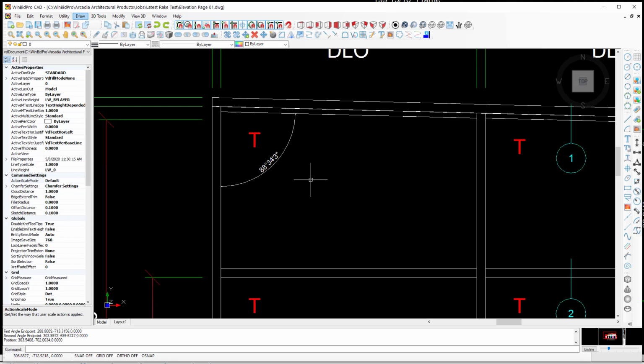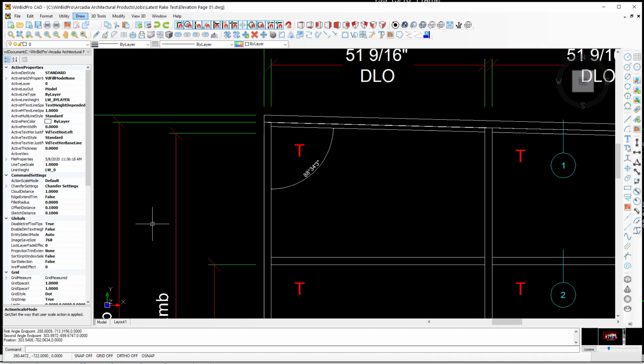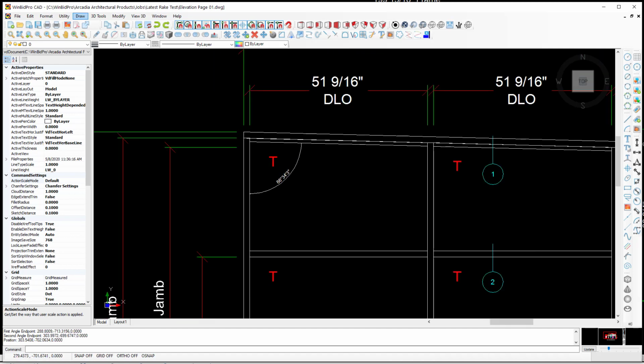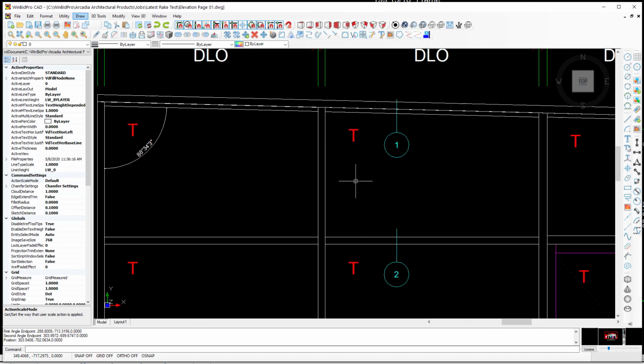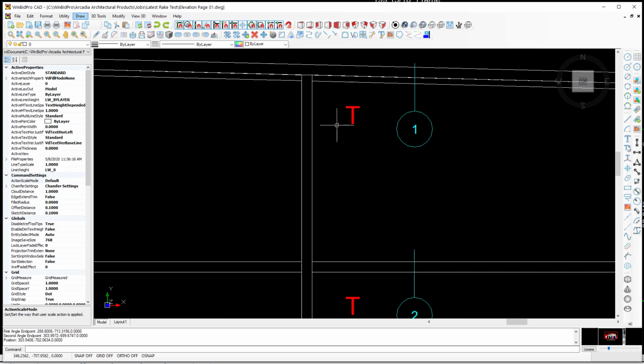Now we're going to work on the formatting of the dimensions after I add my vertical dimensions for the daylight openings, the height of the glass. So I'm going to zoom into this second piece of glass here, and let's put the dimension in on the left side. For this we want to go to vertical dimension over on the toolbar here. So I click vertical dimension. It's going to snap. Now I want to snap in this corner, so it's going to give me the box for that corner.